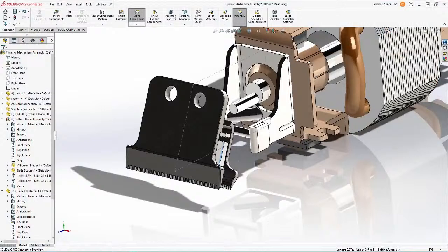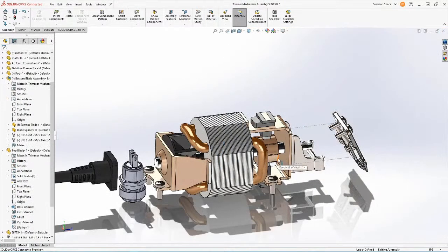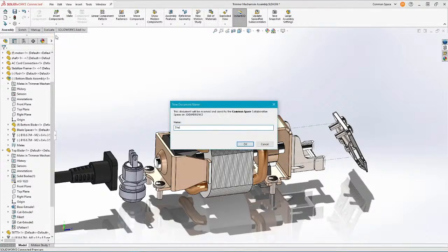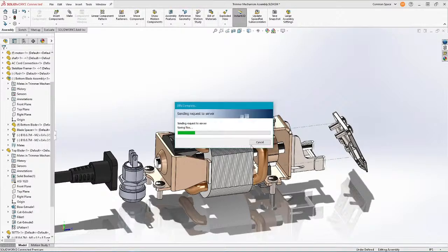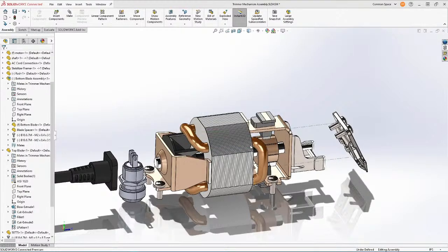So just a quick recap. Again, we need to constrain that side-to-side motion of that blade. So that's exactly what we'll be doing next. To do this, I need to create that new component. So I'm going to do this right in the context of our existing assembly. I'm going to call it shaft connector. And we'll be prompted to choose a face or plane to set as the origin for this new part.